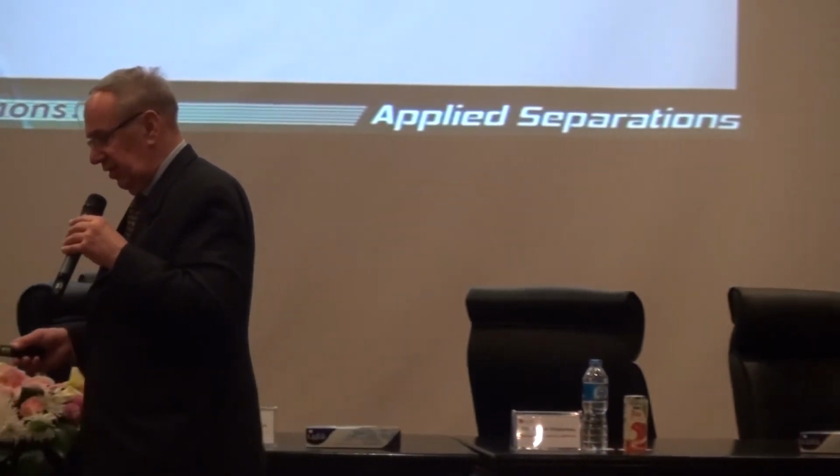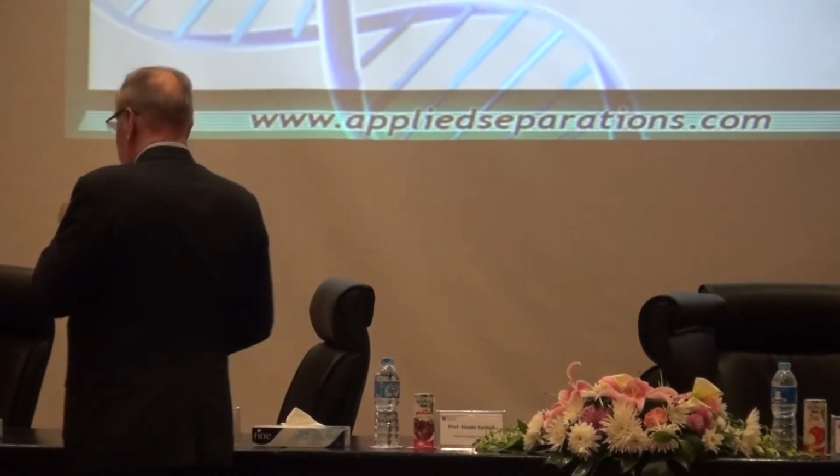Seed oils. These are the ones that are most often used with hexane extractions. For example, the major ones in the U.S., corn oil, are done with hexane extractions. And the problem we always have here is the residue. Typically, although we've gotten better and better at this, even with vacuum distillation and vacuum pulling, we're still often left with 500 to 1,000 parts per million residual solvent. The industry is getting better and better at this, but there's still that residue.